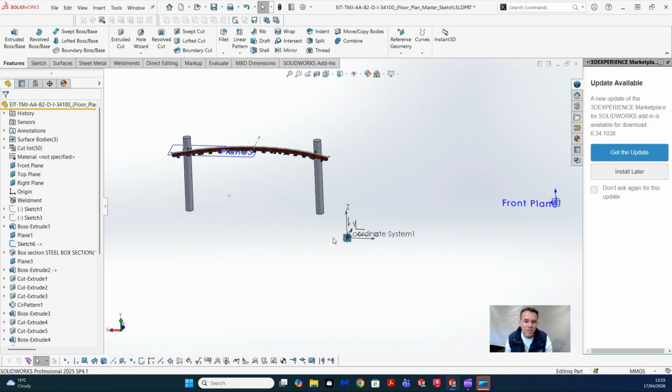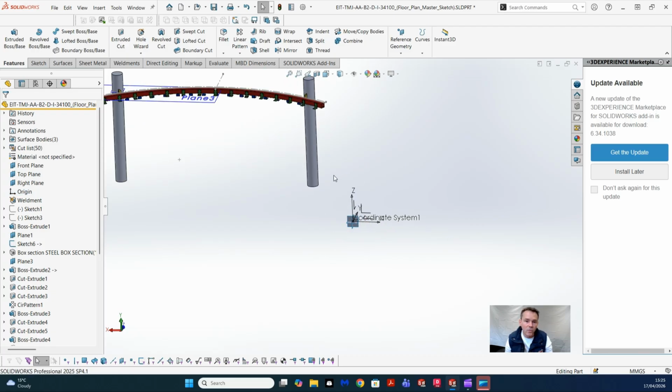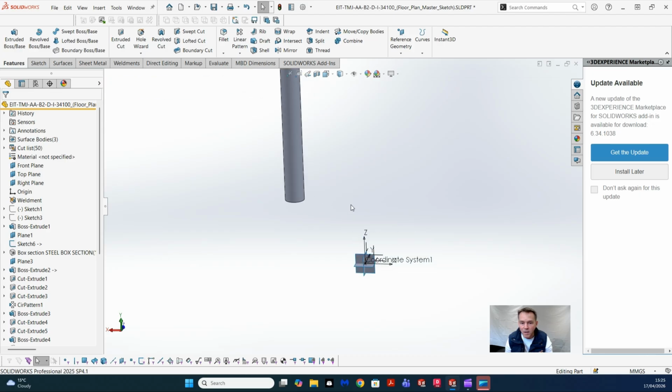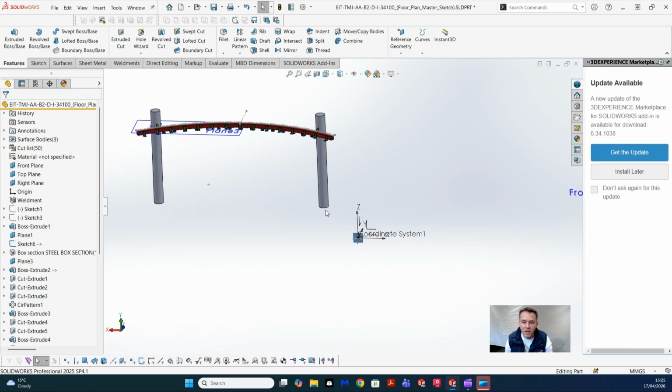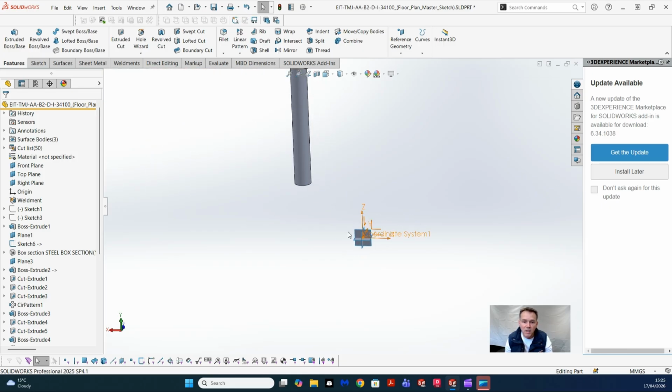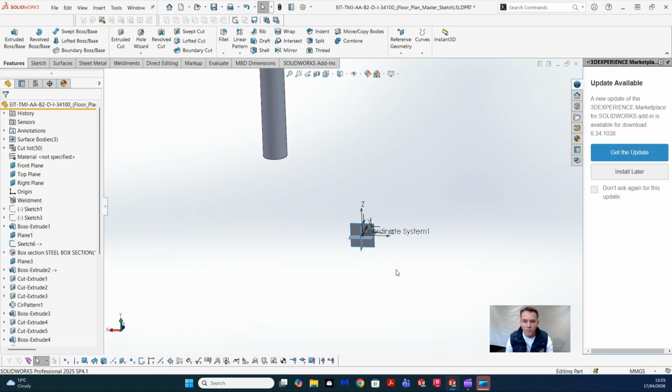Also you'll notice I quite often set up surfaces to create a reference point for parts, for exporting for various things. These surfaces have no thickness, but do add, like a plane, some form of reference that you can hide away.